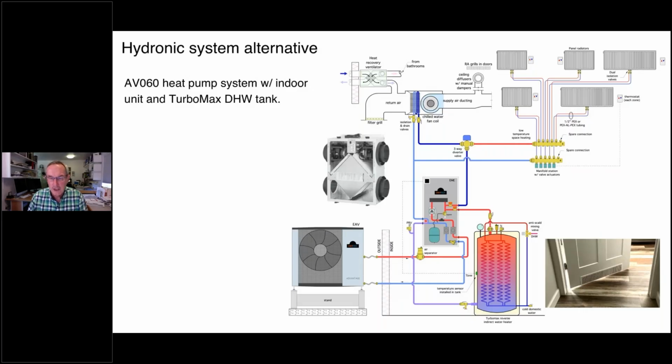If we're in space heating mode, the valve flips to the other direction. And basically, I'm showing it going over to some type of a manifold that supplies panel radiators. Now, again, I'm just picking panel radiators in this example. These could be radiant circuits like radiant floor circuits, radiant walls, radiant ceilings. They could be convector units as well, but panel radiators are designed for space heating only. These are not designed for chilled water. They have no provision to collect condensate.